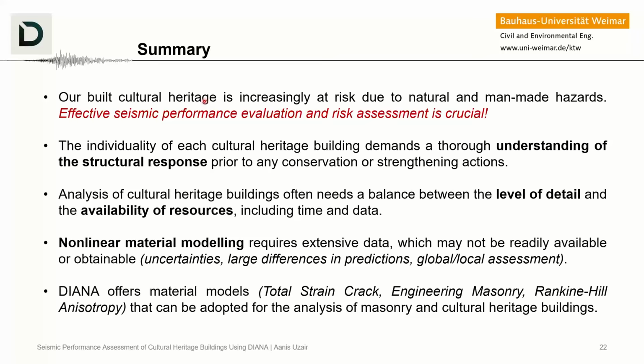The nonlinear material modeling always requires an extensive amount of data, and this is often not readily available to us. And sometimes we are not able to obtain these from experiments because of the cultural heritage aspects of these buildings. This brings uncertainties, and this also brings large differences in the predictions. And then this also limits us to make either a global or a local assessment, depending on the level of availability of data that we have.